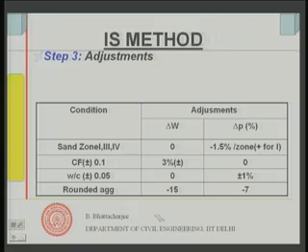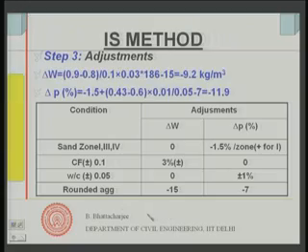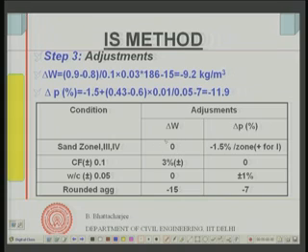Okay. So, the adjustment is done in this manner, we had this table earlier, if you remember. So, delta W, that is the change in the water content, because there is a change in the zone. The adjustment is required because the basic tables are meant for zone 2 sand.